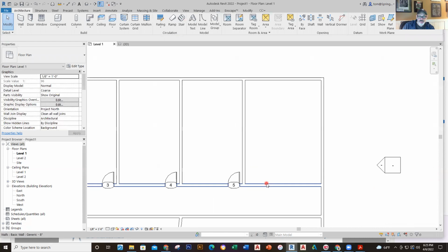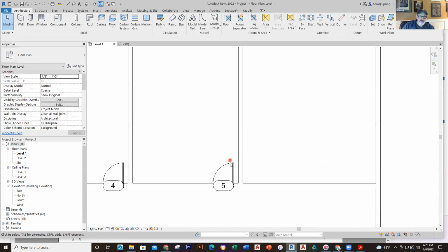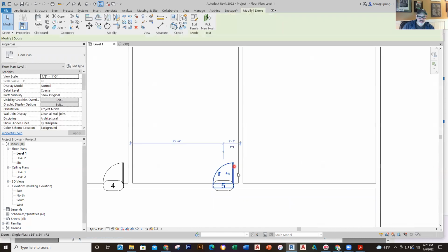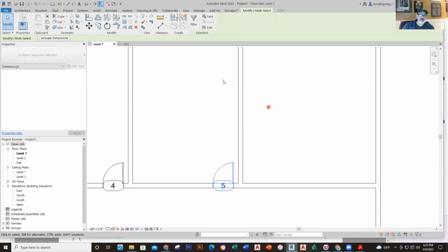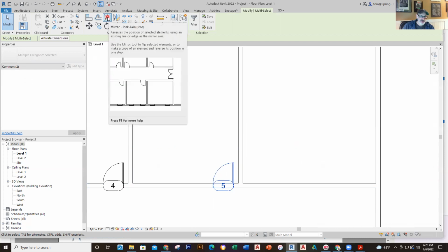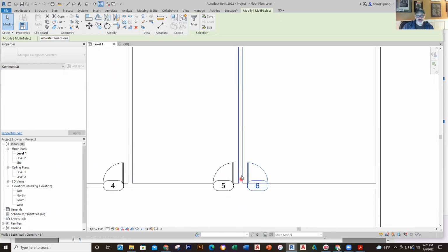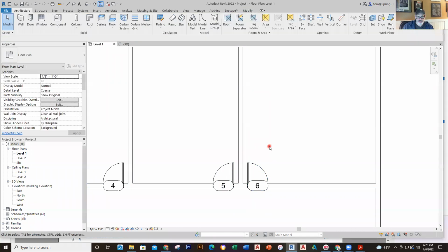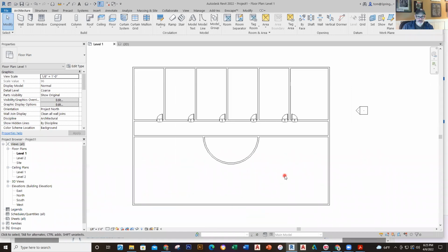Now over here, we've used the mirror command in AutoCAD, and the mirror command would go like this, where I actually would take this object, and I'll click on this object, and then hold down my control key to click this one. And then I'm going to use the mirror command. The mirror command is right here, where I can actually use the mirror to pick the axis. So I go to mirror, and the axis is going to be here, and it goes ahead and mirrors it just like that. I picked the wall right there, and it flipped it right over there. So these are all basic elements that we have there.